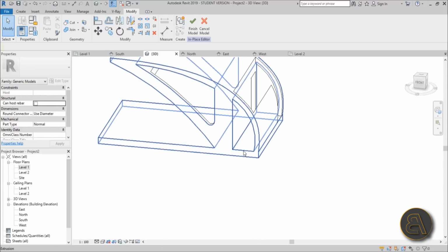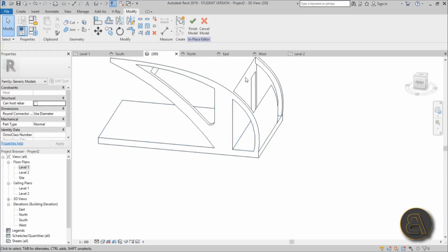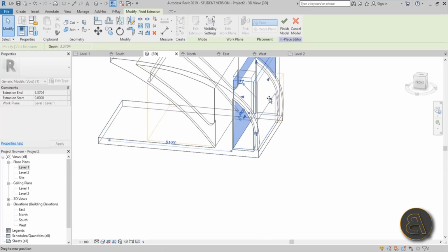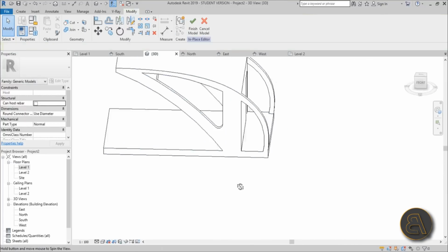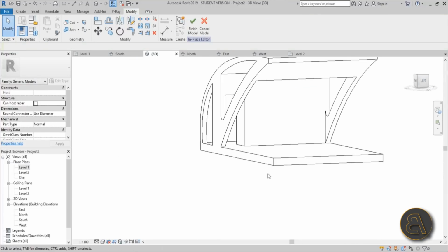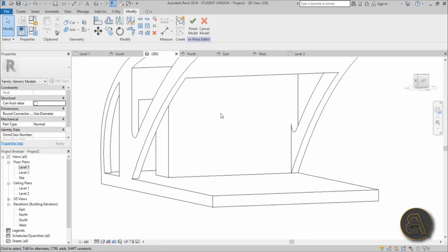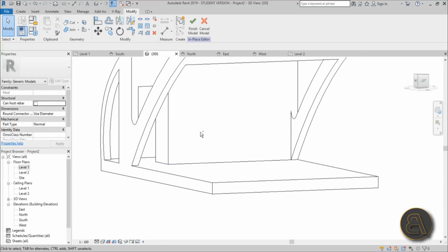So just hover over this edge, tab a few times till you select the void. Okay, here it is, and just extend this part. Okay, and there you go. So we've got this back terrace, we've got this thing, and here is going to be the little indentation for the kitchen in this thick wall. It's not going to be that thick of a wall, that's where we're going to be placing the kitchen.